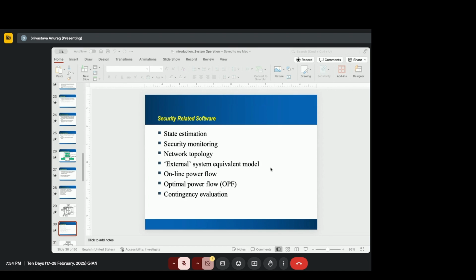And because it's a new substation, it will have a CT and PT which are more accurate, and higher communication bandwidth. So typically, it's not because of PMU versus SCADA, but because of the data input and infrastructure feeding into the PMU that makes the PMU more accurate,